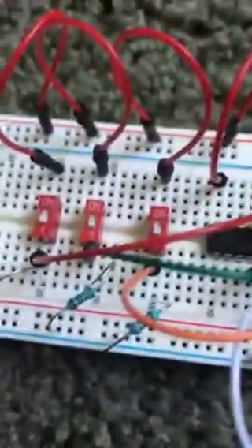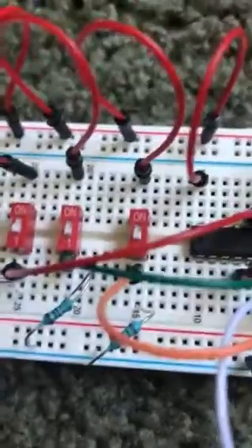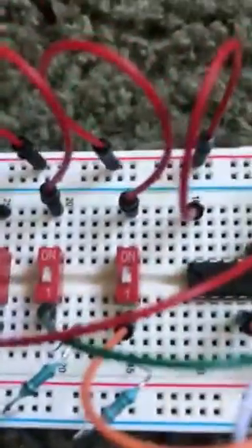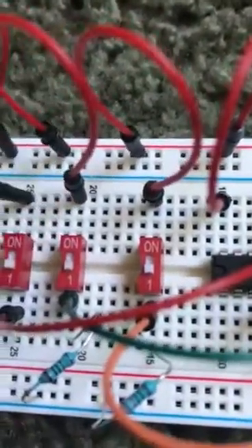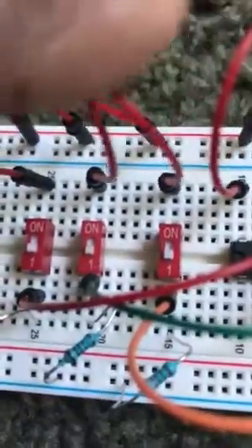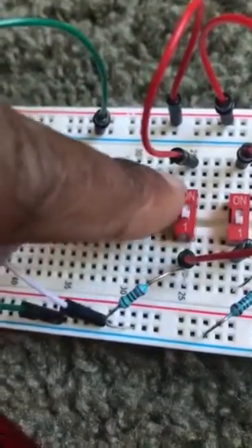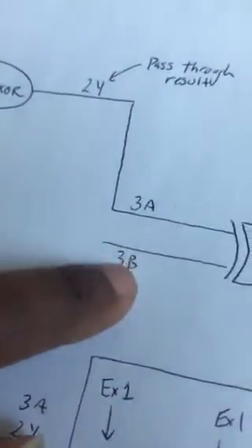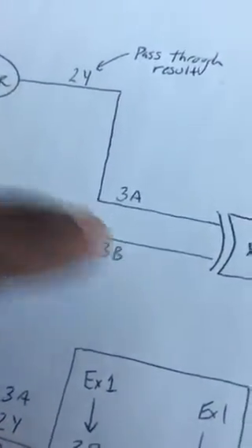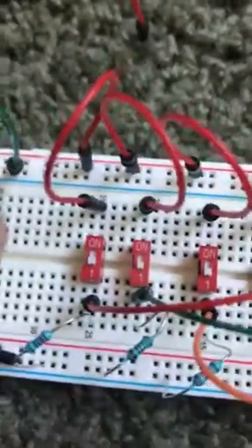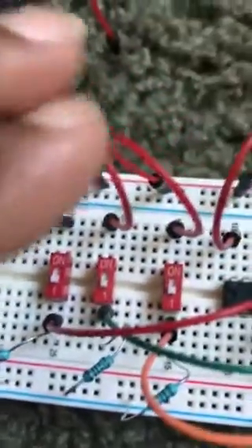All right. So as you can see here, the way I've hooked this up is all switches have to be attached to the power rail. You see here, this is attached to power. This one's attached to power. This third input, for this third switch, which corresponds to this input here, is also connected to power. So all my dip switches are connected to power.